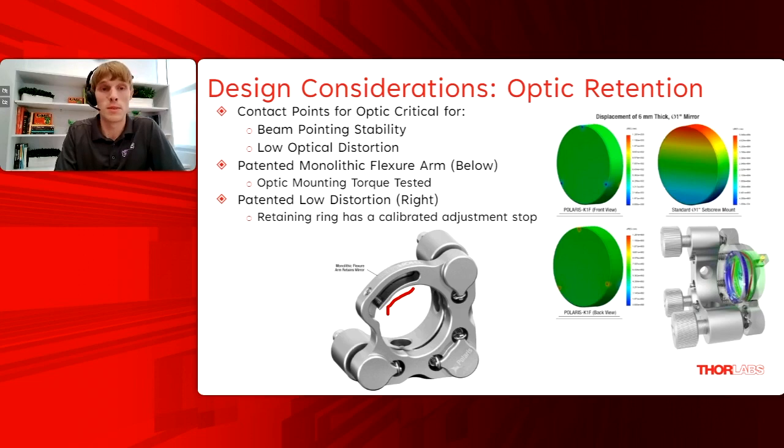We tested these mounts to get the right angle and the right torque for mounting the optic, so that you're able to stably hold your optic in place to keep that pointing stability while minimizing the amount of distortion from too much torque as well.